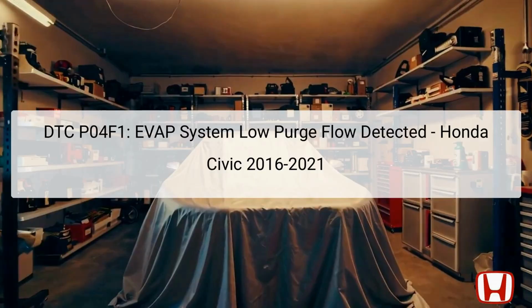The diagnostic trouble code DTC P04F1 indicates an issue within the evaporative emission control system, specifically noting EVAP system low purge flow detected. This issue involves the system that captures and recycles fuel vapors from the fuel tank. The components involved in this system include the EVAP canister, purge valve, vent shut valve, and the fuel tank pressure FTP sensor. The function of the EVAP system is to prevent fuel vapors from escaping into the atmosphere, which can